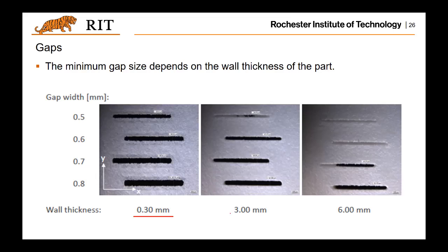But as the minimum wall thickness becomes larger and larger, you will have some thinner gaps filled by the material. That is what you want to be careful about when you have these very thin gaps. And on the other hand, the minimum wall thickness the machine could build is limited. Then you probably want to change your design according to this minimum wall thickness.